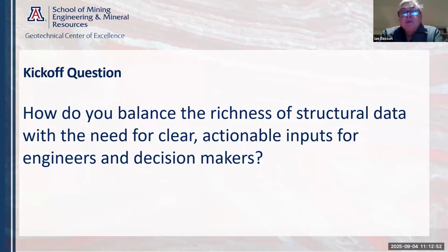So we're at the interface between the rock and the engineer. So it's our job to try and communicate that. I agree with everything that's been said, but communication is essential. It's not just enough to show them a stereonet with a robust data set that's statistically significant. You need to communicate to the engineer what that thing means. We're dealing with natural systems. It's not a building or a bridge.